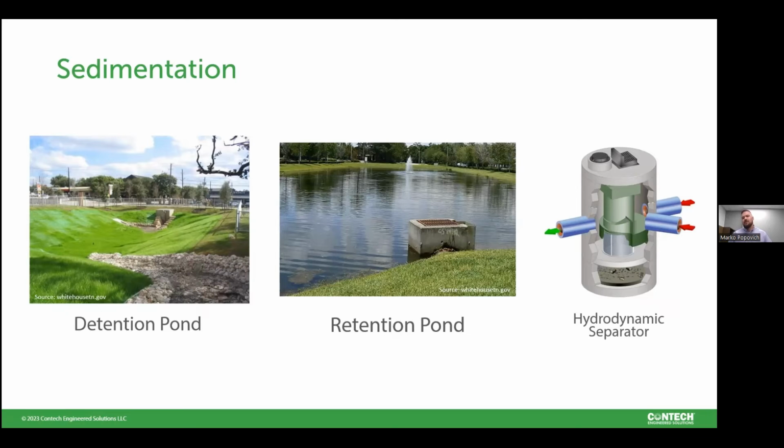The reason a hydrodynamic separator is viable and used is land, available space. We ultimately don't have a lot of space in urban areas. So consolidating it, paving parking spots, putting buildings, whatever else you may need, it helps us take the forebay from a pond and put it within a separator and get that actual treatment component of the water quality attributed in a smaller footprint there.